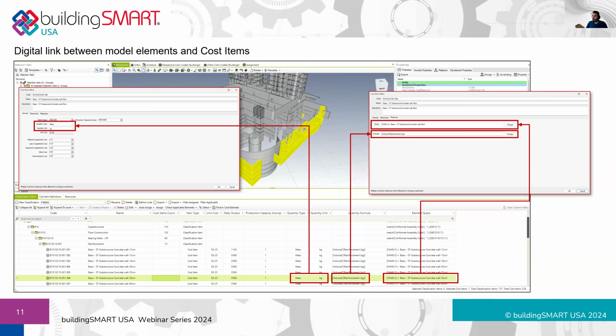relevant. Another side of it, so one thing is that we need to relate elements to the cost item, cost description, cost name, cost code. We also should provide calculation of the item's quantity based on the quantitative data that is mentioned in Mr. Pilgrim's paper, so that your estimation quantity is also tied to the model elements, and that with the change and modification of the model, your quantities and your calculation in your budget is changing as well.